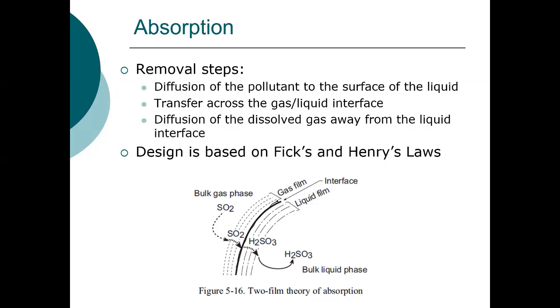Well, the whole design of these systems is based on Fick's law, which says that the rate of transfer is equal to a mass transfer coefficient times the difference between the driving force, where Y is the concentration in the gas phase and Y star is the equilibrium concentration, that is, the concentration of that chemical in equilibrium with the concentration in the aqueous phase.